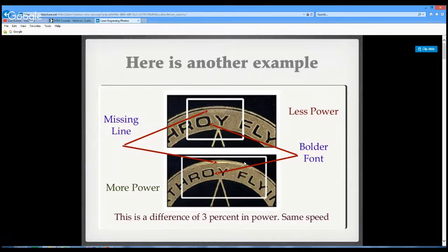You might need a little bit more power for the maple than you do for the pine. So it's certainly machine specific depending on the wattage of your machine, but it's also product specific too. And we'll maybe show a couple of images when we're actually lasering the photo so you can see the difference, whether it's on acrylic or on wood. I've got a couple of different woods here that we can show.